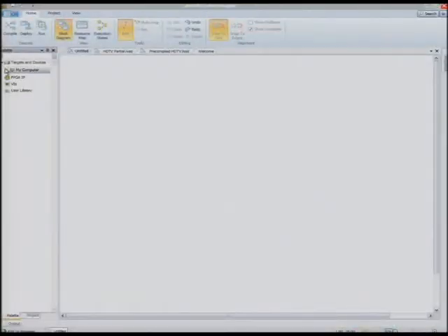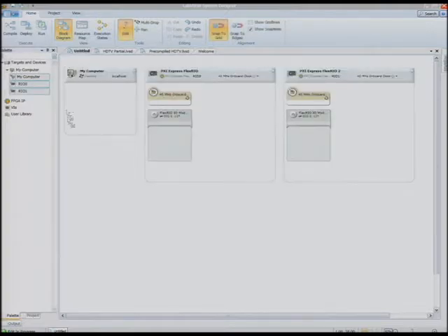Great, so now that we know about our hardware for our application, let's dive into the LabVIEW System Designer to see how we can visualize and configure the hardware in our system. First, in the editor on the left-hand side, you'll notice that we have a palette that displays the hardware available to us in our system. We'll go and drag that onto the diagram, and you'll see nodes that represent our Windows PXI controller and our 2 FlexRIO devices. In addition, we display hardware components that are specific to each device.